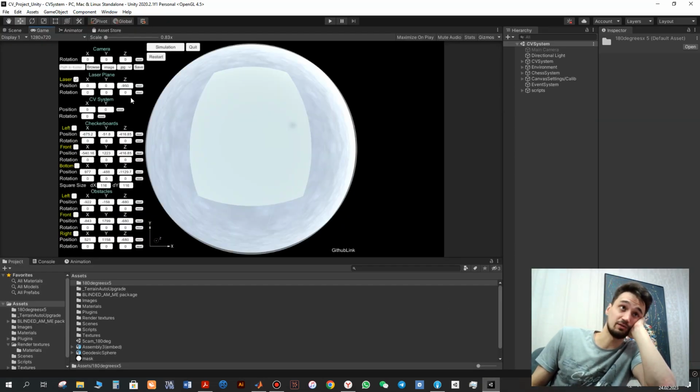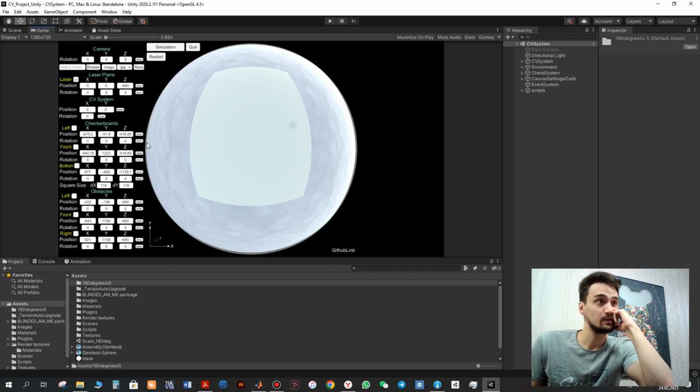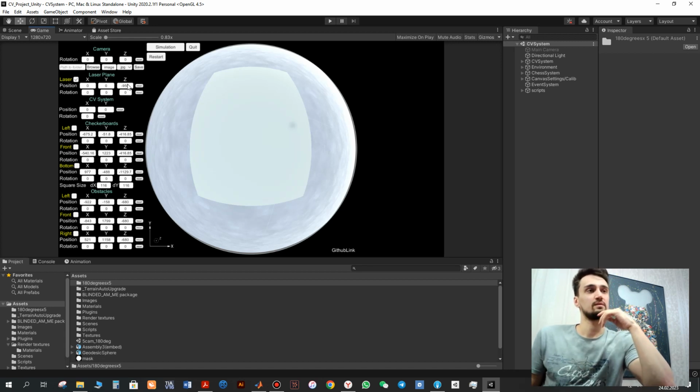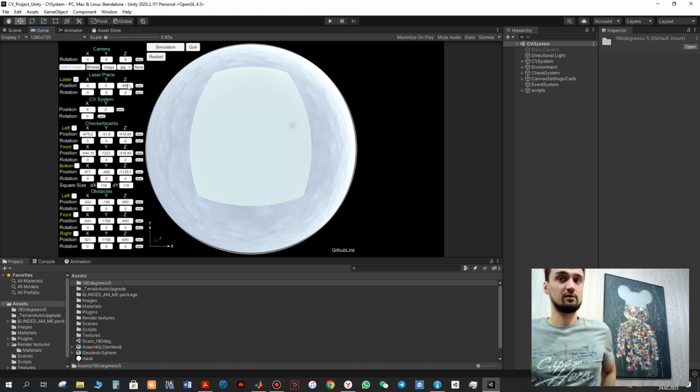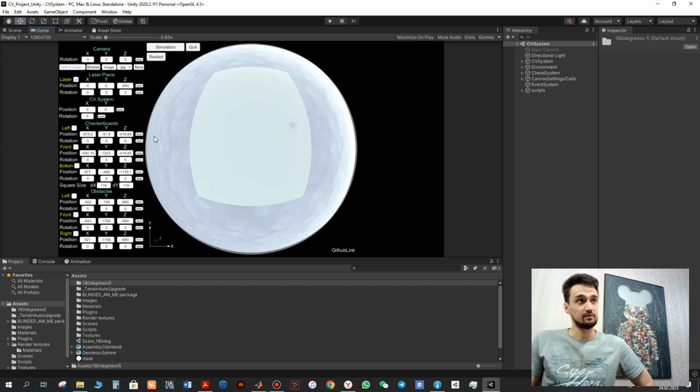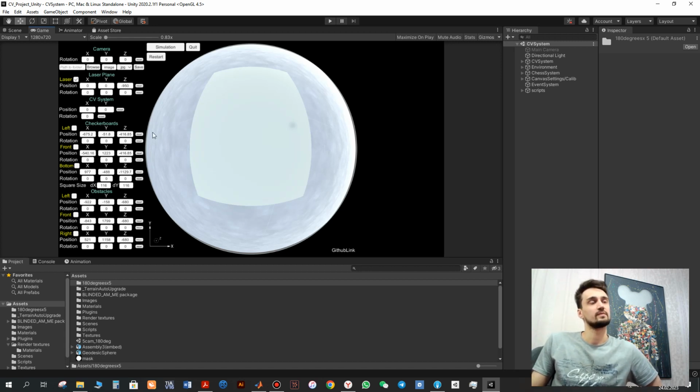We worked with them just to understand how to compose these matrices, but in real cases it won't be possible to know the distance between the camera and laser plane. We can measure it manually, but we can get some errors. Also, we won't know the real camera orientation and the real laser plane orientation. So we can get them with calibration data.